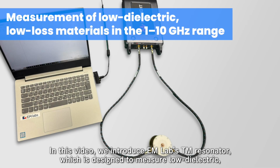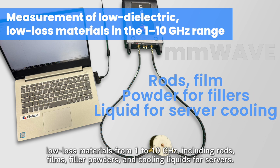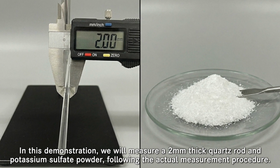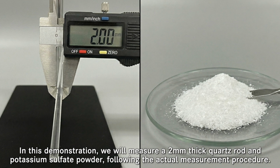In this video, we introduce EM Lab's TM Resonator, which is designed to measure low dielectric, low-loss materials from 1 to 10 GHz, including rods, films, filler powders, and cooling liquids for servers. In this demonstration, we will measure a 2 mm thick quartz rod and potassium sulfate powder, following the actual measurement